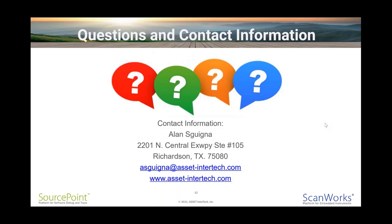Okay, thank you, Alan. The next question is, could you summarize the main differences between debugging on AMD and Intel CPUs? Yeah, certainly. Both platforms are very similar. A lot of what you saw today on the EPYC platform, on the AMD platform, is common with both Intel and AMD. The main difference between the two platforms from a debug or JTAG point of view is that Intel has a number of trace features that EPYC lacks.